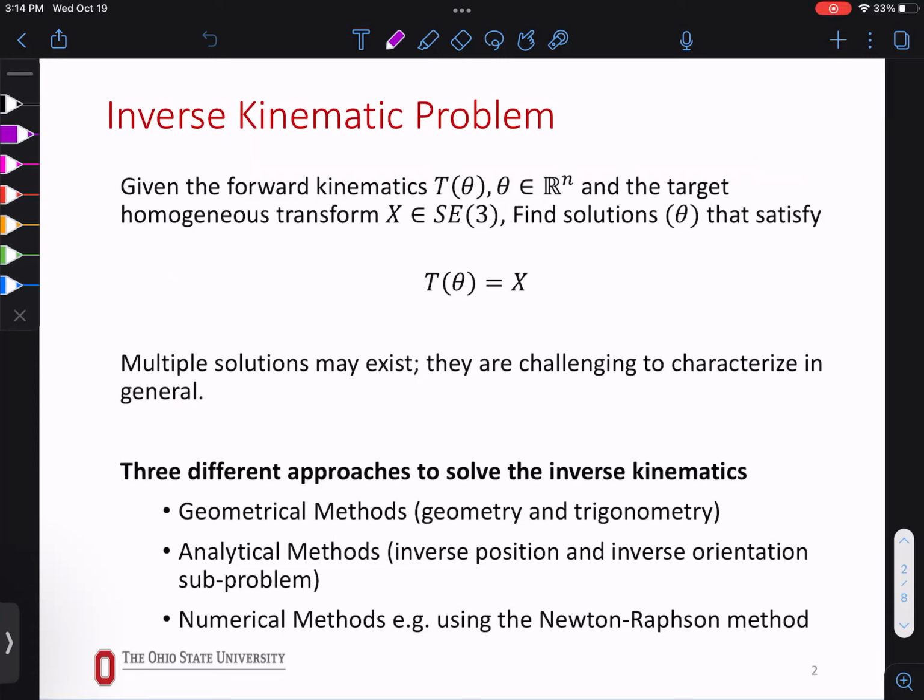All right. If you're following the book, I think this will show up, and then this. I found it very useful. It's not from your book, but the premise is very simple. Again, the task of inverse kinematics is, given a forward kinematic, the position and orientation of your end effector, or where it should end up, can we find a solution for the joint variables that satisfies that forward kinematic?